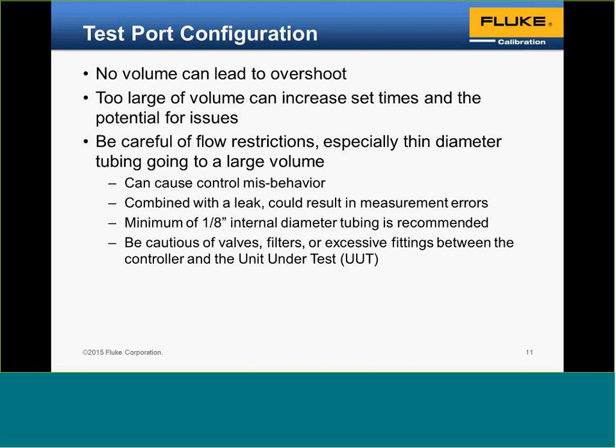Beware of flow restrictions, especially small diameter tubing going into a large volume on your test port. You'll see the small tubing, small volume, but in reality, it's trying to fill a large volume on the very end.